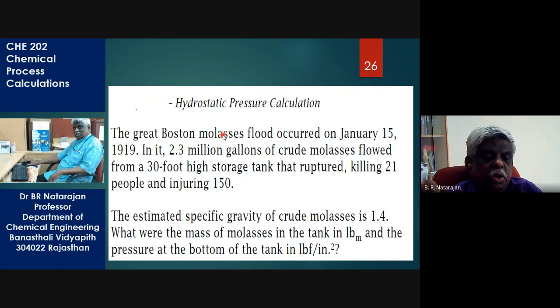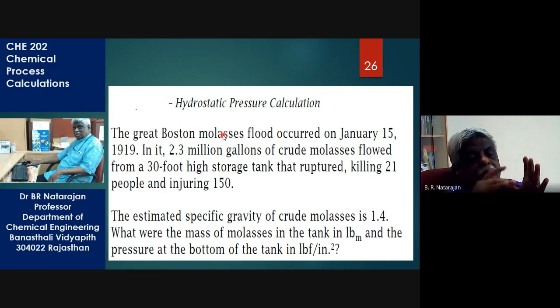But if it is in the sugar factory, after filtering, it goes for concentration where the water content is reduced and it is made into a concentrated sugar syrup, where you may use Brix scale to measure, remember, and then it goes for crystallization, right? And then sugar crystals are formed.